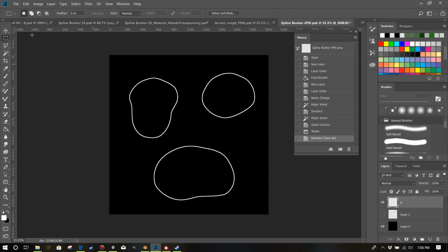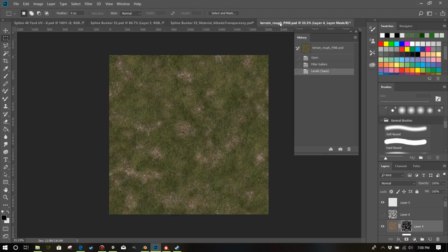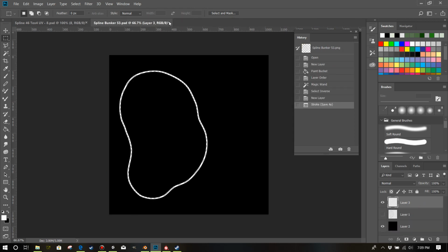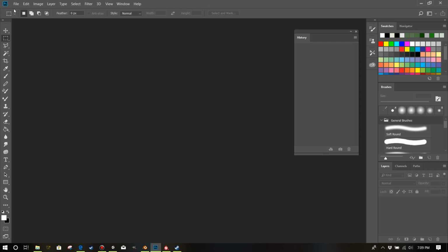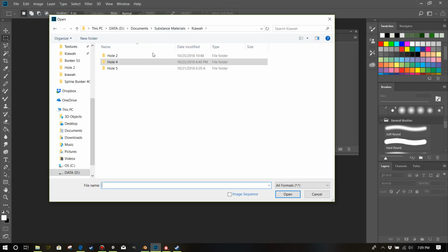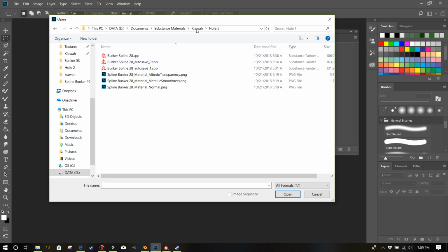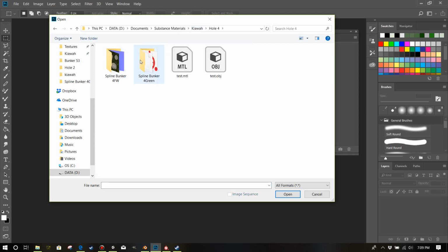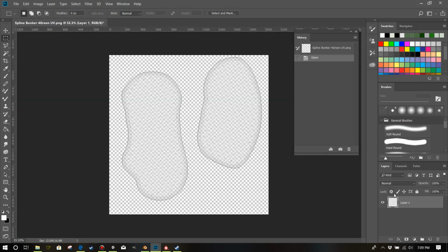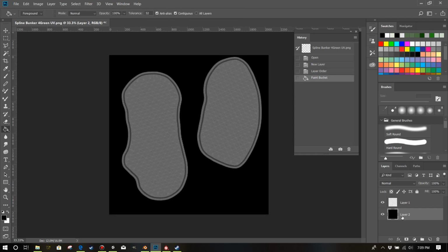And now I'm going to go into Photoshop while it's working on that. And we're going to create a mask. And so what I'm going to do is I'm going to open that UV map that we made, or that we exported, and bring that in. So this was our UVs, and I'm going to create a layer and put it underneath here and paint it black. So get your paint bucket and fill that in black.